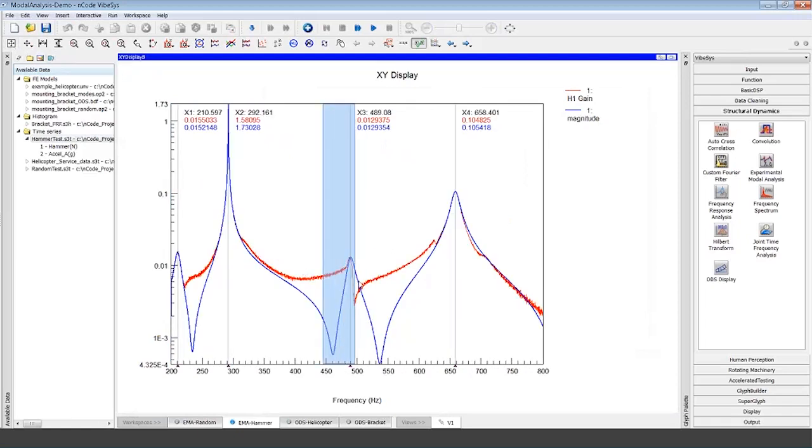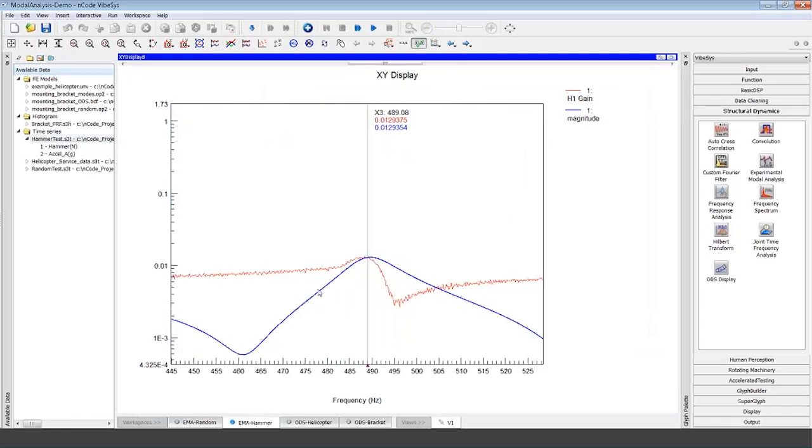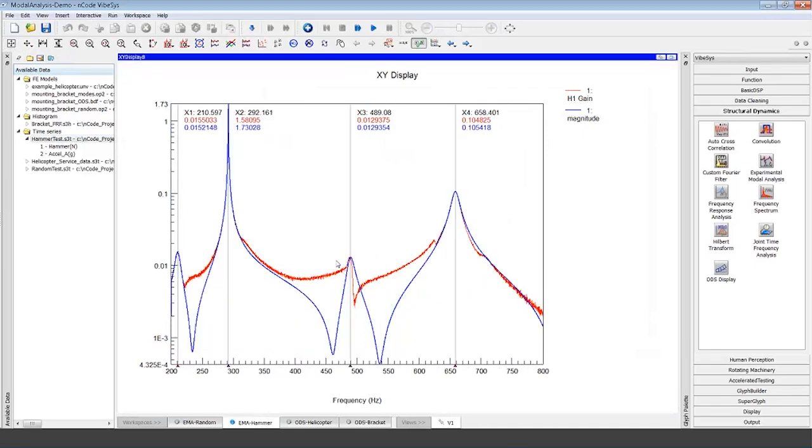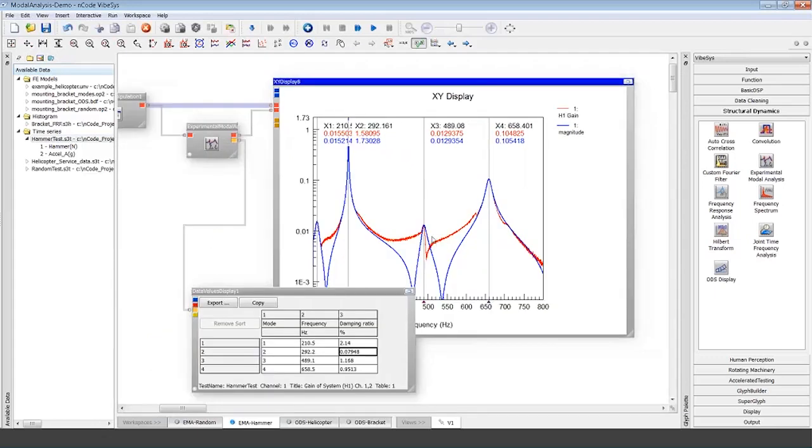This one in the middle that was captured, maybe not as good, but I think it's acceptable. Still, again, better than when you do an FEA analysis and leave the default value for damping coefficient. I'd rather use the one that it's calculating here. So we've got this result here, and we think by looking at this plot that they're fairly reliable.